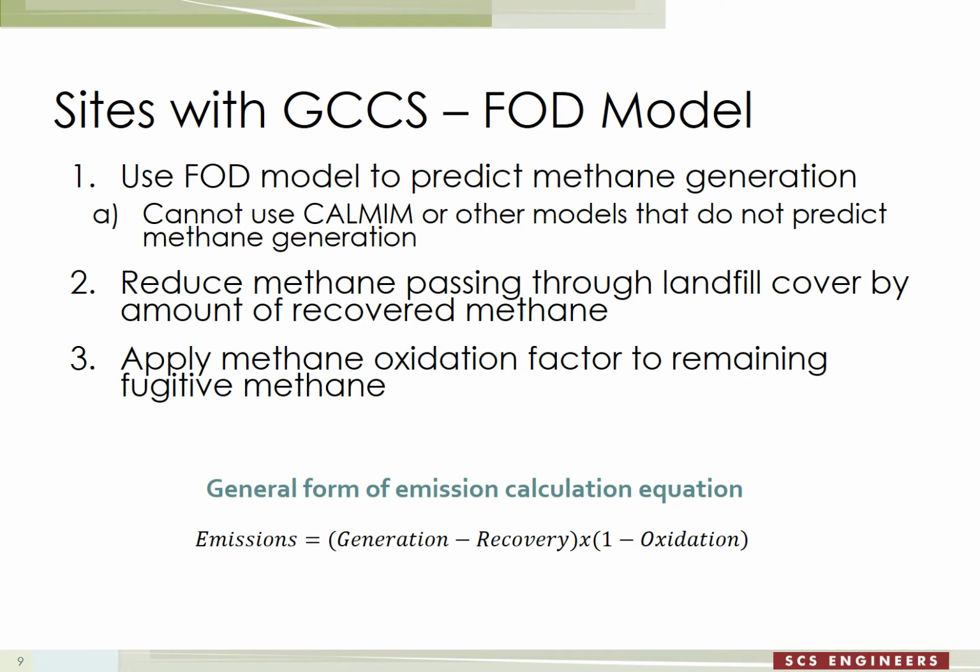So that does mean you have to rely on the first order decay model, and that, we already talked about the error that introduces. Although the uncollected methane could be emitted, we know not all of it is, because regardless of whether they have a gas system or not, there is a portion of the methane that is oxidized in the landfill cover, and so that factor is applied to that uncollected or fugitive amount of methane to ultimately estimate what we consider to be the emissions of methane from a landfill.